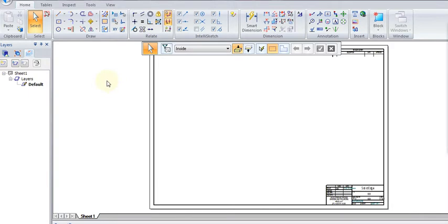So the drawing tools that we're going to look at mainly are the line tool, the rectangle tool, the circle tool, the fillet tool, and we'll look at some of the relations or constraints. So we're actually going to use these tools to put together a drawing of a simple bracket. And as we go through creating the bracket, we'll see how we use each of the tools. So let's just identify where the tools are first and look at how the drawing container is actually accessed.